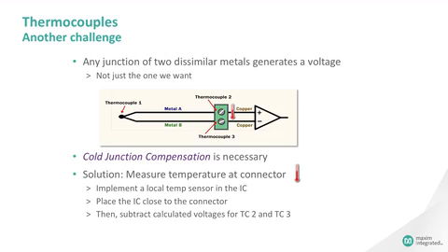Before the advent of low-cost temperature sensors, the approach taken was to keep the two unwanted thermocouples at a constant temperature, typically using an ice bath. Then, the voltage generated by both the unwanted thermocouples is known and can be subtracted from the total voltage presented to the measuring circuit. The temperature at thermocouple 1 can then be calculated from the resulting net voltage.